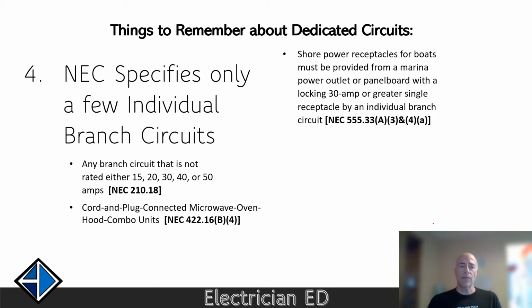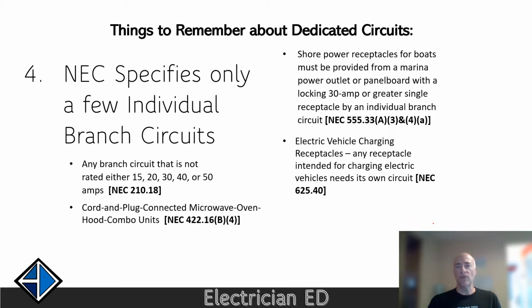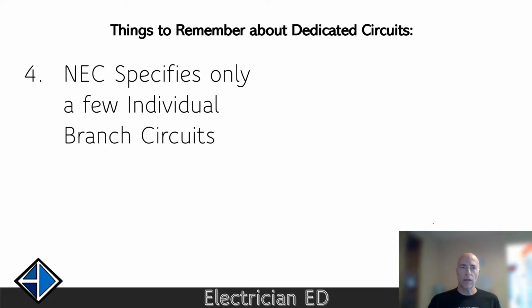Or if you have an electric vehicle charging receptacle, any receptacle that's intended for charging electric vehicles has to have its own circuit. Okay, and if you have a hydro massage bathtub, that's another one. Manufacturer's instructions often ask for a GFCI protected, dedicated, or they may say individual circuit to power the pumps and other components of the hydro massage tub. And that's in line with the NEC requirements as well.